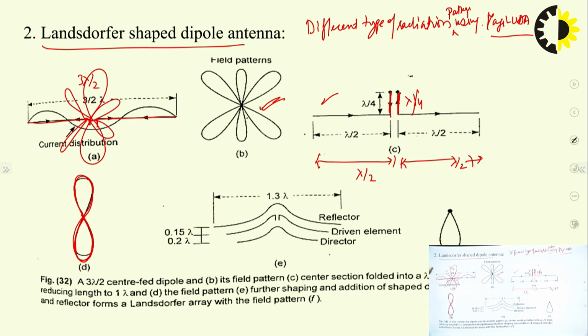So to improve the radiation pattern of this antenna, we will change the length of the dipole antenna in one particular direction. So you will get this type of antenna, which has no side lobes or other lobes, only a lobe at 0 degree or 180 degree.